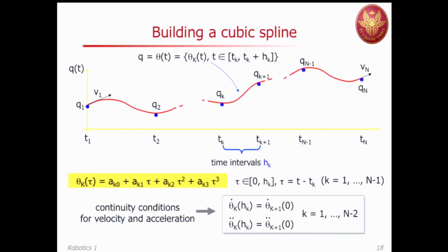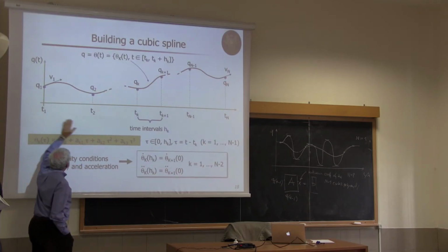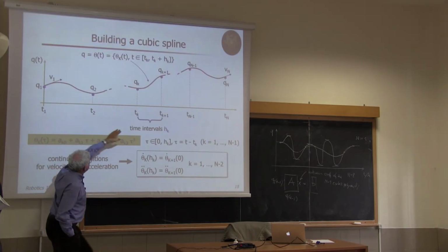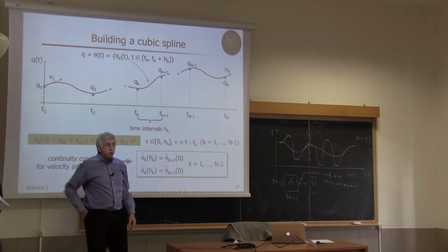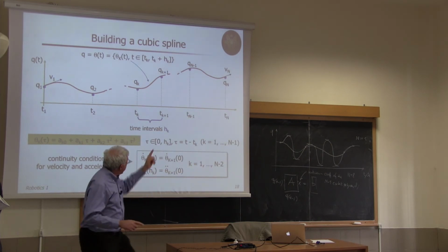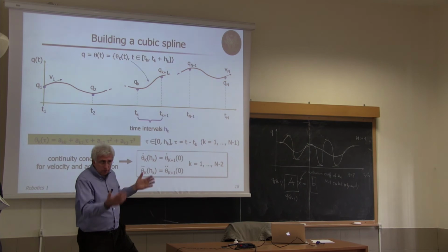And here I'm imposing some initial velocity, because this time I can talk about velocity, not just tangent or path derivative. So V1 is there and Vn is there. 0 or not, pay attention, it could be anything. And now I'm specifying also the time instants, so T1, T2, Tk, Tk plus 1 up to Tn. So the total traveling time will be Tn minus T1. T1 is typically 0, so Tn is the total time.